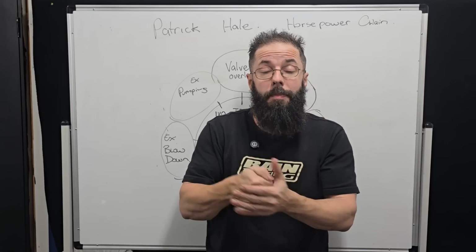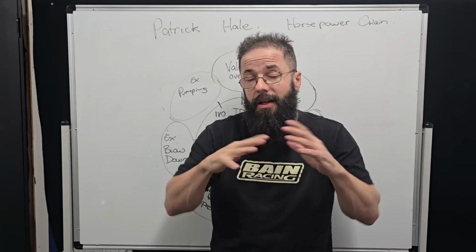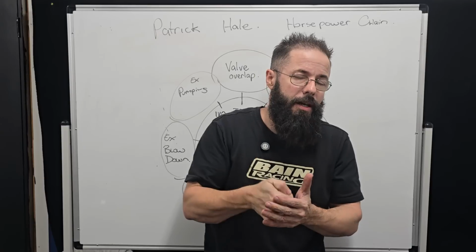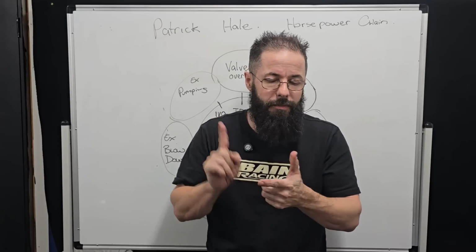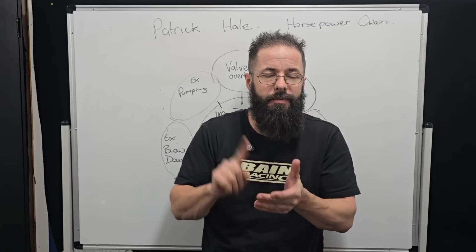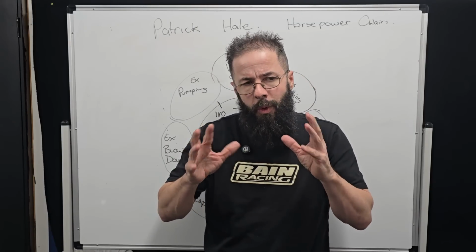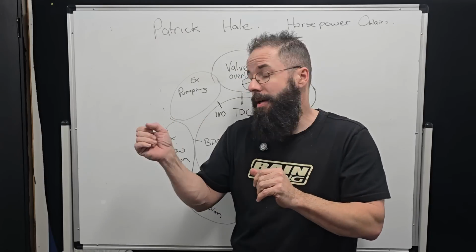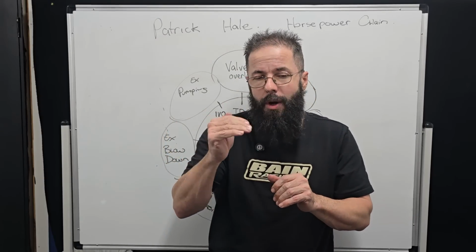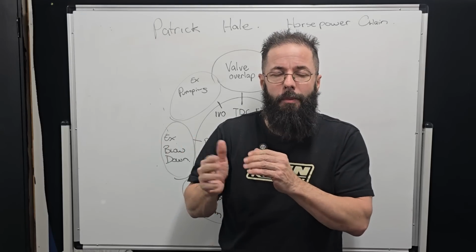We opened it too early. And opening it too early, you're fighting cylinder force, because remember, we're fighting a hell of a lot of cylinder pressure there. If you do open it too early, then you're smashing camshafts, you're ripping the nose off the cam, you're snapping camshafts. There's all sorts of problems that can come into that. So we really need to understand how important our blowdown phase is, the point of opening. So that's not the most important part, but it's a very important part.